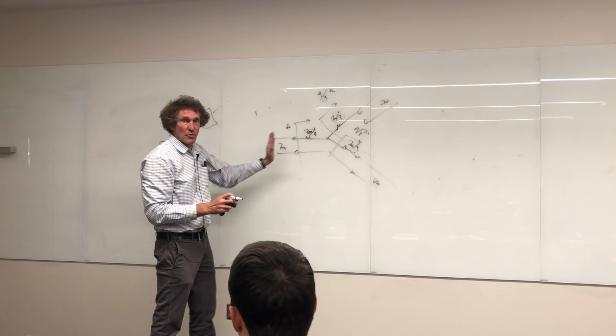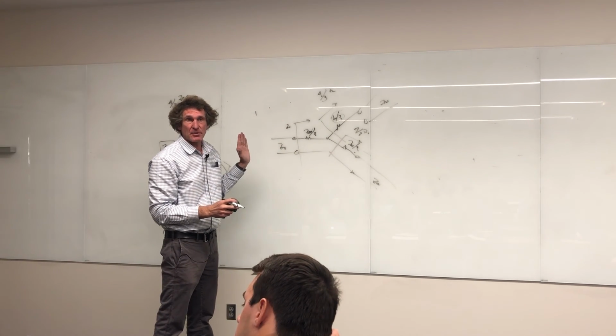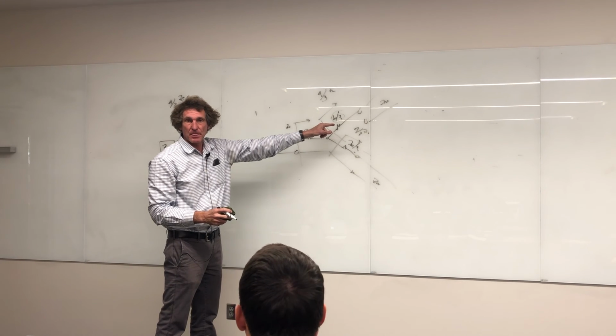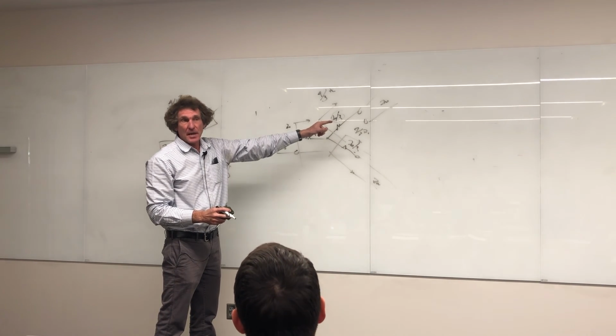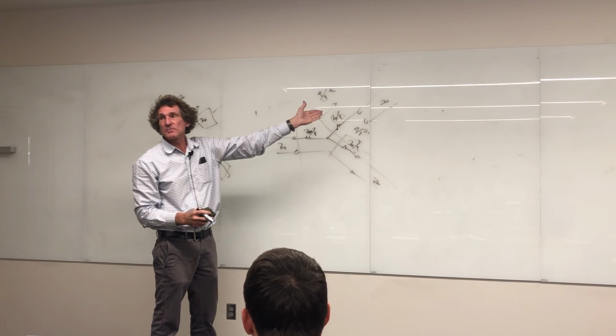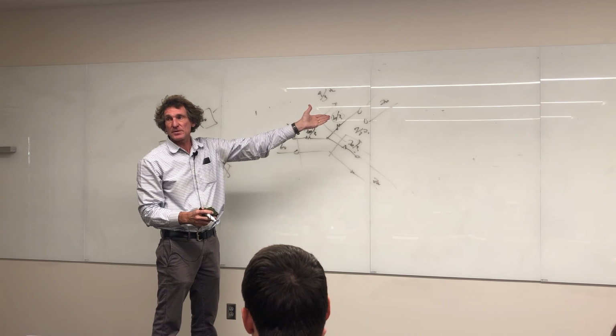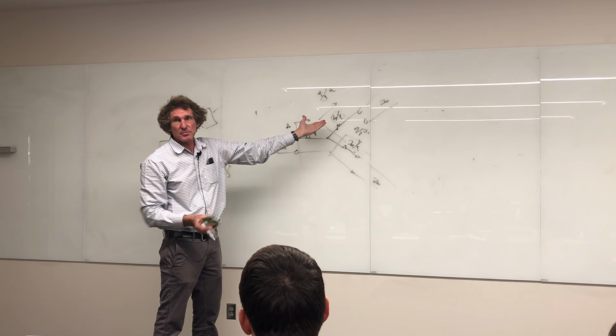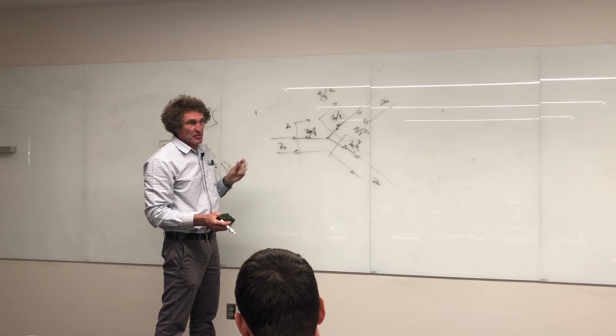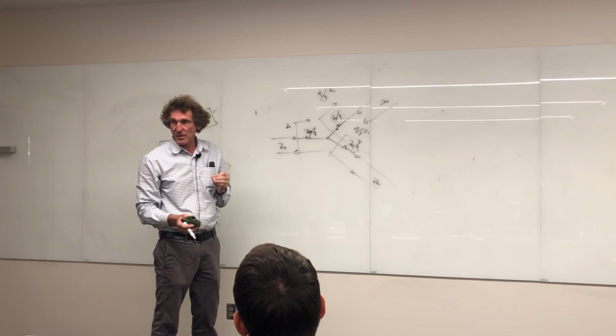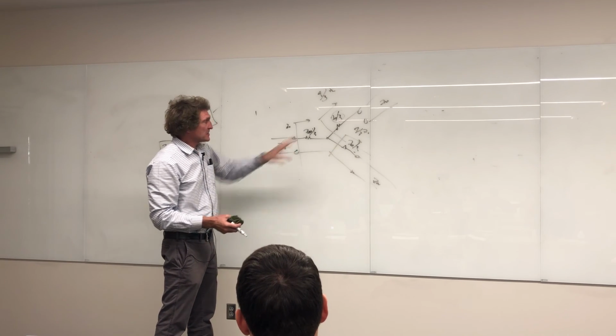This is one way to get no reflections. That will do it, but now you're losing all this power here and here. So you're losing a lot of power. And now your S21 is not 1, it's greatly reduced. Do you all follow me in this class? Even if we did a power split without these, it would still be a problem with impedance matching. You get an even worse problem. But that's the reason this is bad.